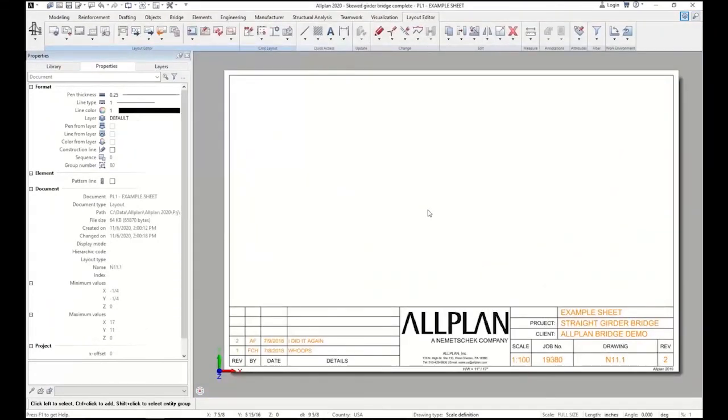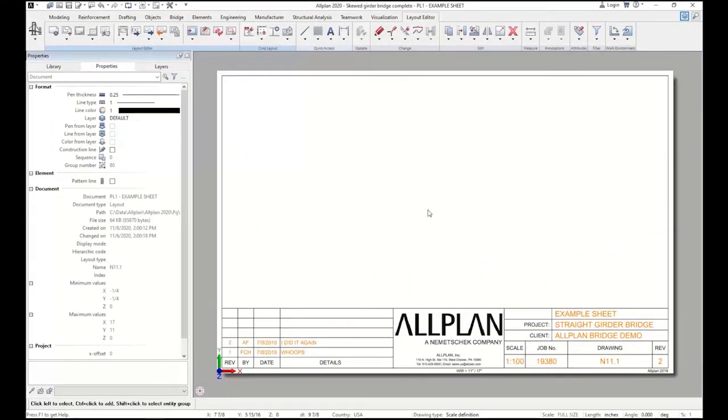All right, so now we're going to go to the layout editor of a completed project. And it works just like you expect already in the paper space or layout space that you have in your other drafting programs. Some things you might not be used to is an automated title block. So just like we can apply attributes or read attributes from any of our objects, whether it's a volume, a Z height, what have you, you can attach your own attributes. Those of you coming from BIM, you know this. We even have layout and project attributes, which can, of course, go on and inform all of these different aspects of our title block here.